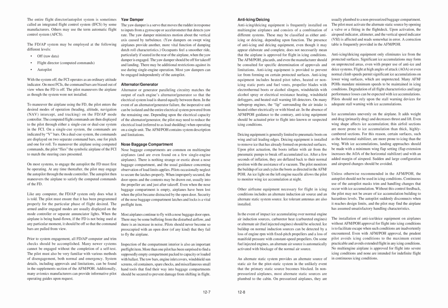Even with AFM/POH approval, the prudent pilot avoids icing conditions to the maximum extent practicable and avoids extended flight in any icing conditions. No multi-engine airplane is approved for flight into severe icing conditions, and none are intended for indefinite flight in continuous icing conditions.